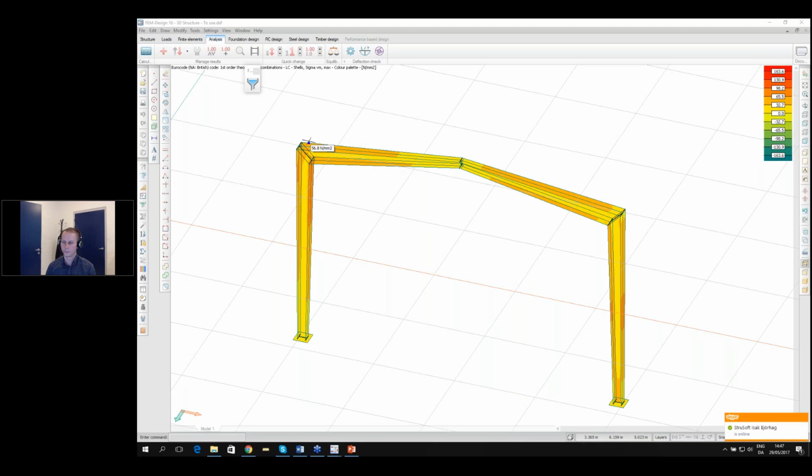And Klaus writes to me in Danish that he would like a little information about how to model with the right center lines. But Klaus, you made an amazing Excel sheet to calculate this. Because if you model from A to B on a line and make it a shell, it will be 50% on one side and 50% on the other side of this line typically, if you don't play with the eccentricity in both ends. And it can be a bit difficult to calculate this eccentricity, but it can be done.